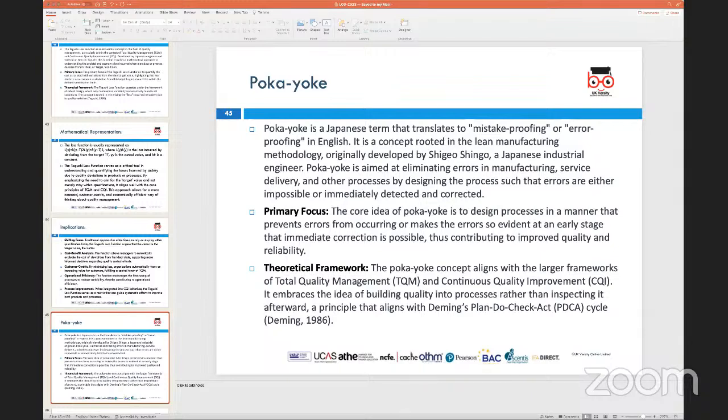And one of the key principles behind the poka-yoke technique is to make it easier for the operators to perform the task correctly. So when you look at a lot of people working within factories and they are required to work with specialist machines to produce goods, one such example is shoe manufacturing or sports shoe manufacturing by Reebok and Nike and Adidas and a lot of other brands, you would generally see that there are various parts of the shoe which are being assembled using different machinery by different operators.